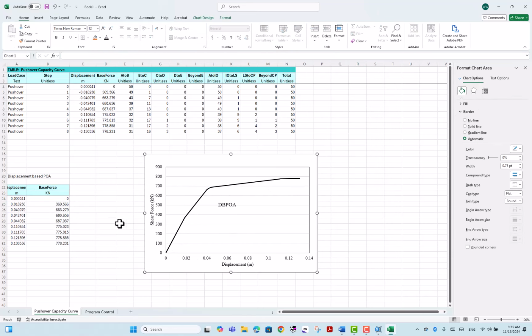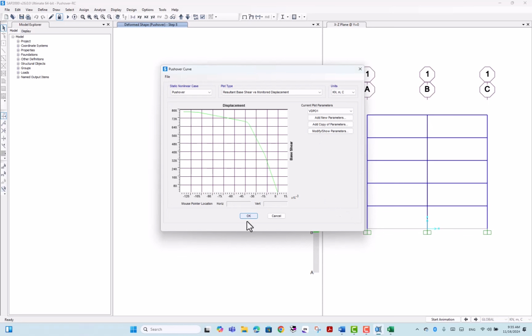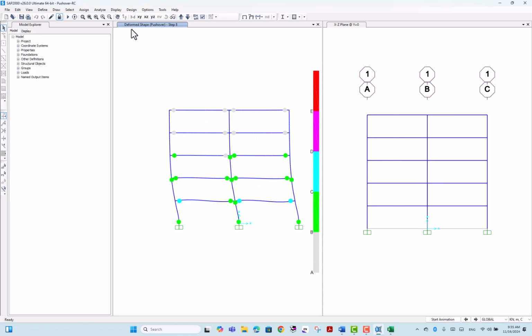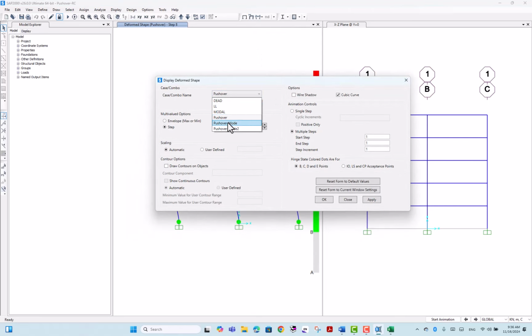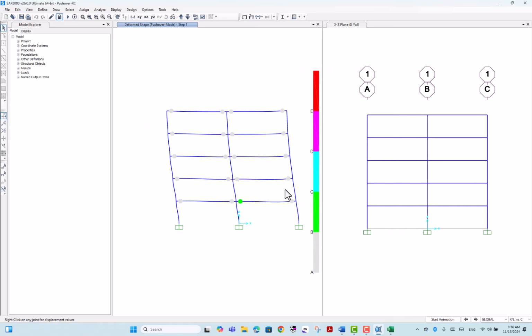So we finished the first one, and we go to check back, so it's okay. We go to the second analysis. So remember, the displacement and the force may be similar, but the hinge pattern will not appear the same. So we're going to run pushover based on the first mode shape, and that's good, we have the mode shape also. So we go to the first step, which is the same point, and the second, we have totally 8.